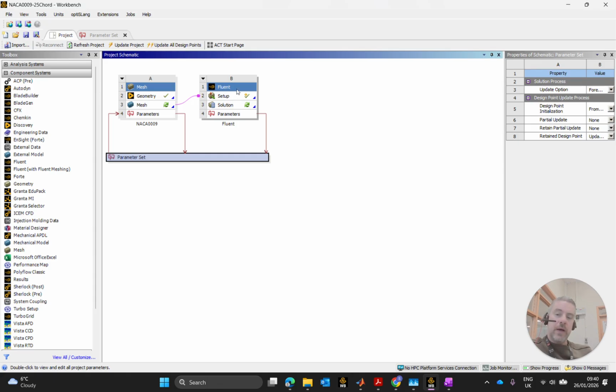If we have that, then we'd have all the tools in Fluent to calculate both P, which is the apparent order, the numerical behavior of our mesh, as well as GCSI, the grid convergence index, which gives us a level of confidence that our discretization is good for the scheme, the turbulence model and the model we have set up, to a level of confidence, if you like. We can calculate all that in Fluent, and that's fine.